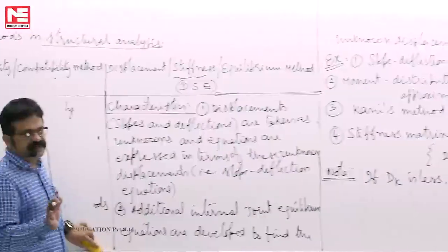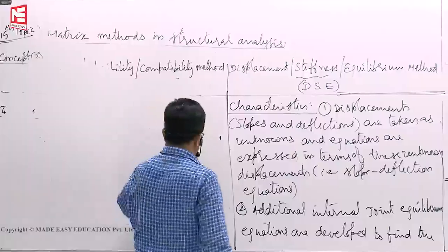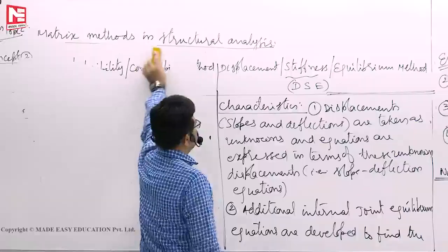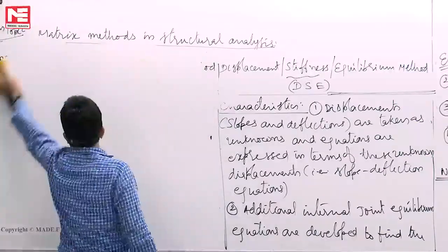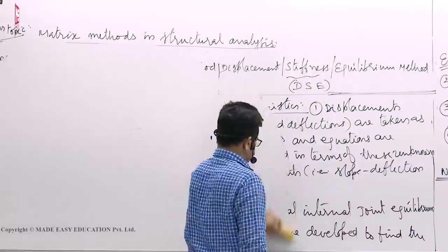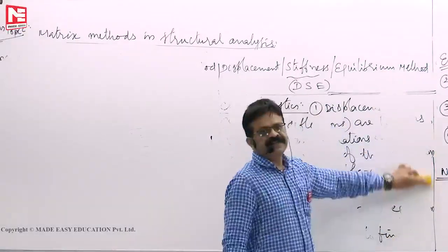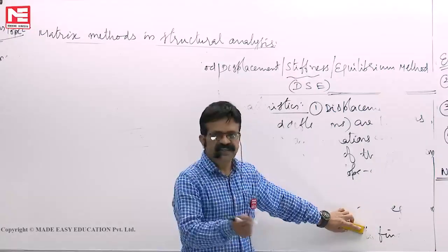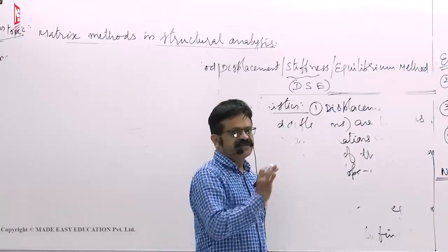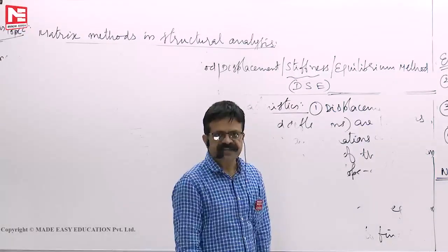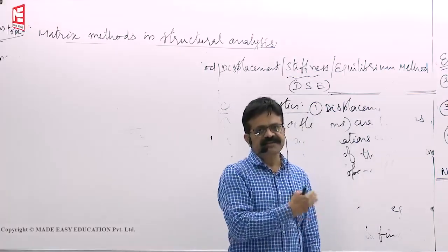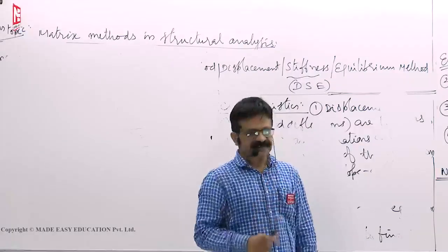Energy methods I have given you completely, whatever we have studied. Some come under the force method, some come under the displacement method or stiffness method. There are Castigliano's theorem 1 and theorem 2, that's it. At our BTech level, we have only linear elastic structures. That's why Castigliano's theorems 1 and 2 are enough. The Crotti-Engesser theorem we don't have to use. We never used it because we didn't deal with material nonlinearity or geometric nonlinearity at BTech level.